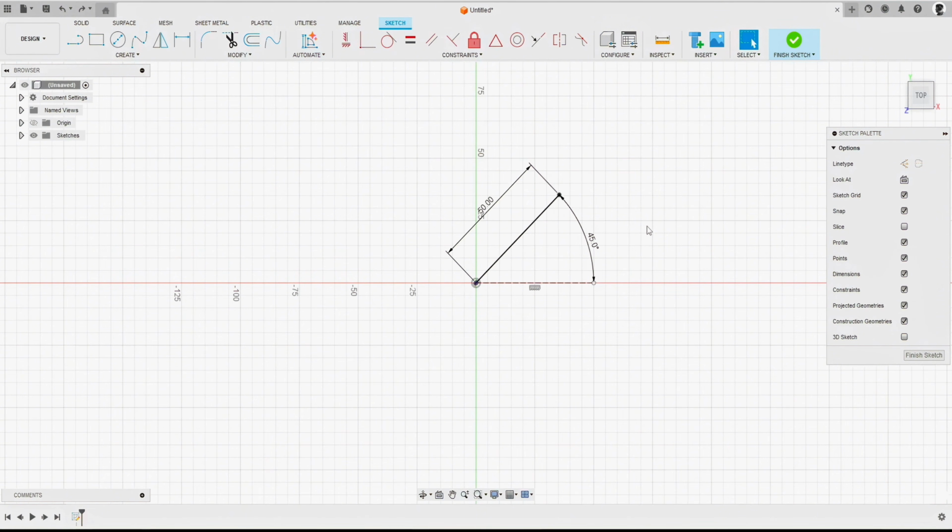Now we're back to our 50mm linear and 45-degree angle line. Let's continue sketching them. I'm going to hit L on the keyboard again, go back to the line tool. I'm going to bring the mouse over and snap onto the end of our line here, for that blue box up here. I'm going to drag to the right-hand side, and you'll see we're snapping to the grid.